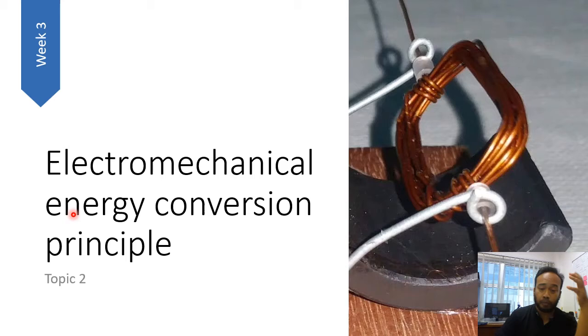MMF is the product of the number of turns multiplied by the current, or what we call current density. So, the current that you circulate into your winding to push that magnetic flux through your magnetic circuit. And that amount of magnetic energy is consumed mostly for the flux to go through what we call the air gap, right? We looked at the relation that is analogous to Ohm's law: the MMF equals the flux multiplied by the total reluctance.